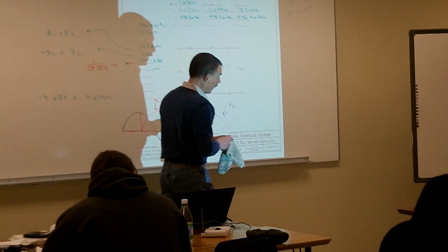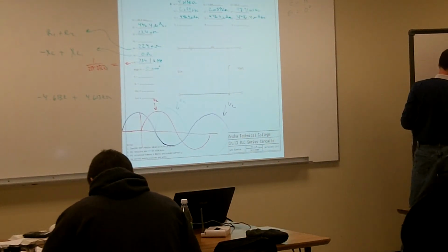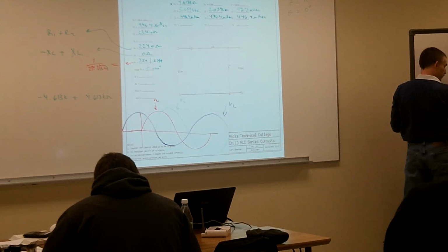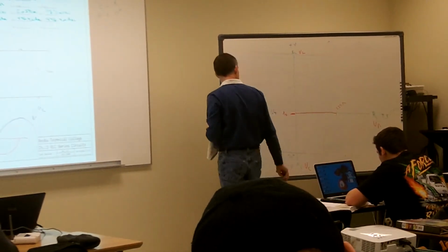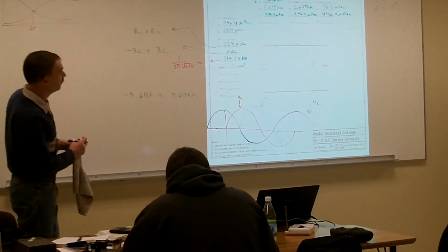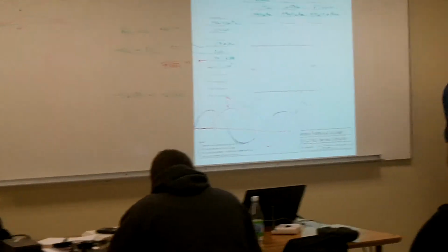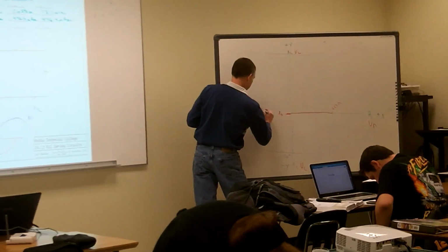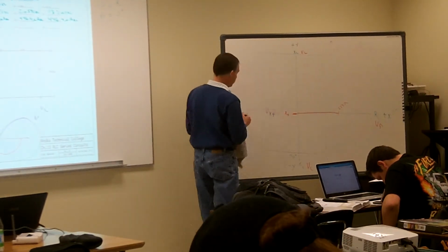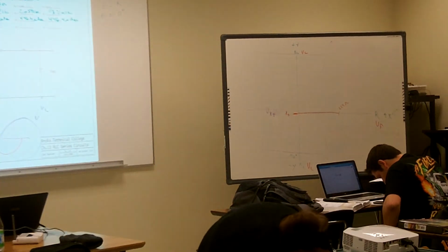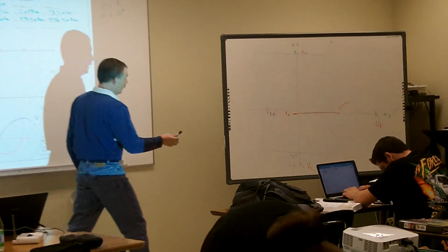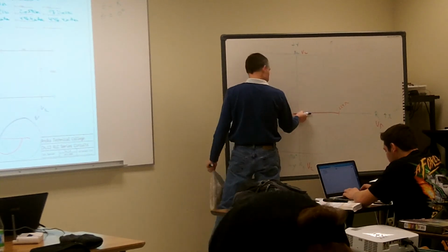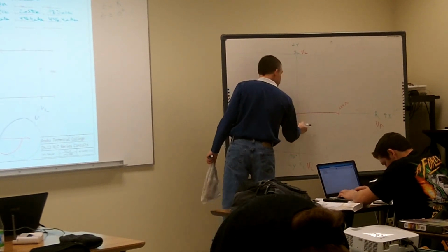And that's why we can just go ahead and take our V total, which is the same thing right here. We just cancel those things out. We can just algebraically add them together, take my VC plus VL, and that gets me my voltage total of 0 volts. Or rather, the voltage of my passive reactance total would be 0 volts, not my source voltage. So we put that one right on the 0 there. My VS is going to be somewhere in between, but if I cancel those two out, it's going to be sitting right on top of VR.